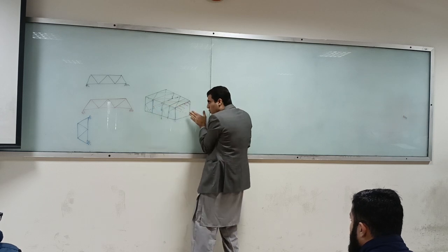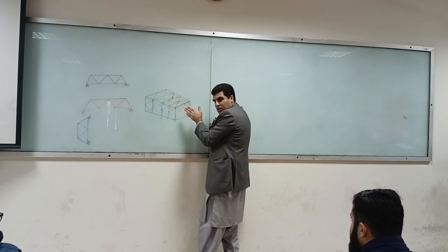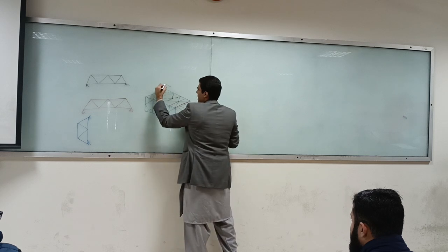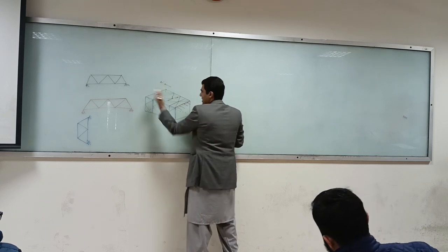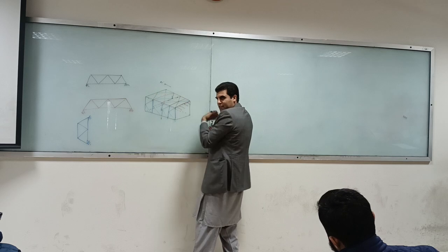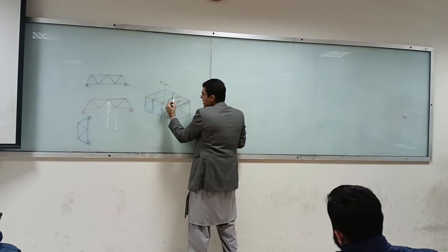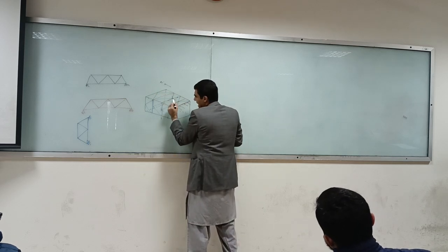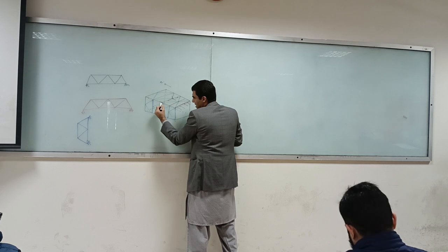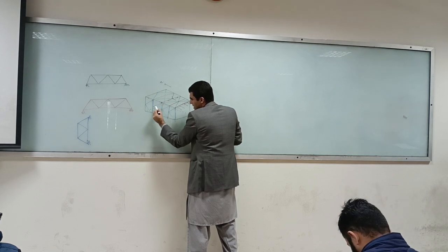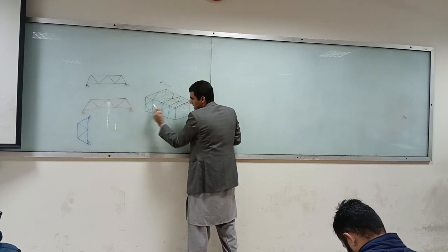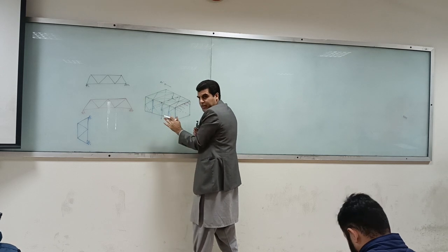So you have provided the, imagine if this is my north direction. So in the north-south direction, I have provided my load path. So anyway you take lateral load, that lateral load will be taken by this, and then from here it can come down over here nicely through these trusses.